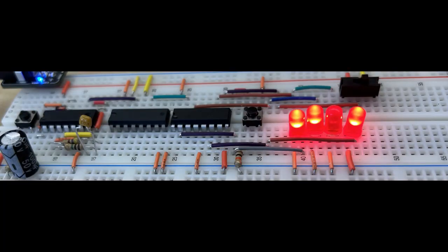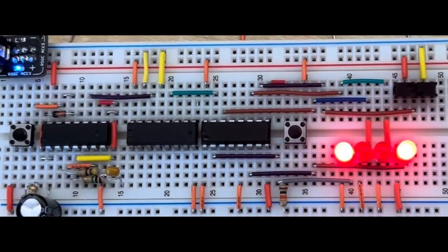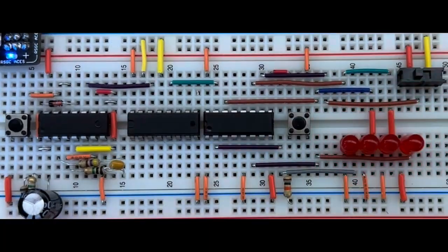Next, the decimal counting binary up-down counter. This circuit features the 4510 chip. This circuit takes the carryout of the decade counter and turns it into binary counting. This circuit can count from either 0 to 15 or 15 to 0, depending on how it is conditioned. It represents the numbers in binary.